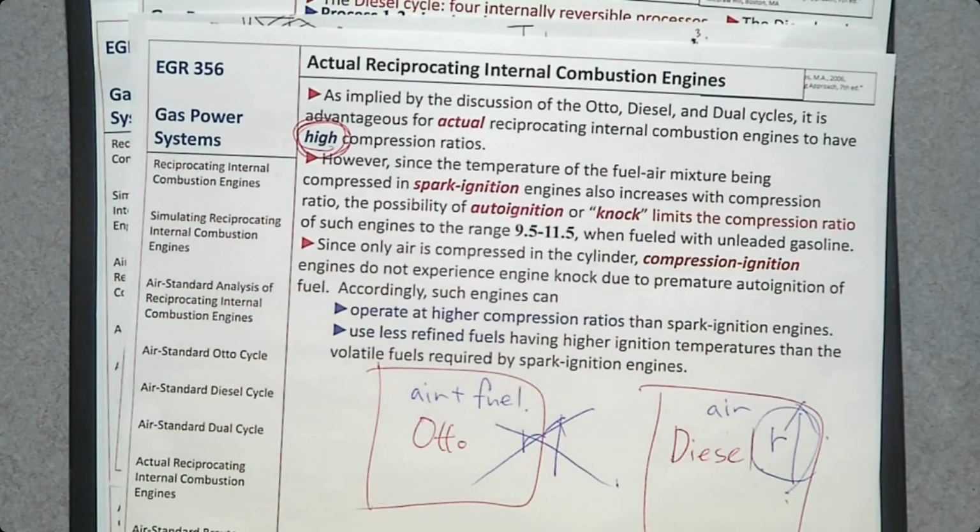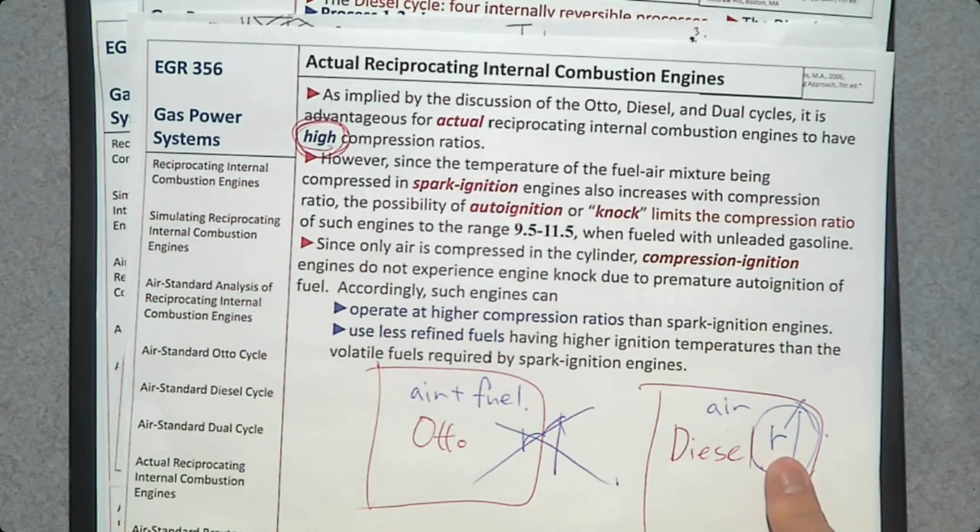Simply, you mix them, air and fuel, and inject into the engine, which is simple. However, to improve the compression ratio, you don't mix them, just inject air and then compress as much as you can. And when it is the right time to have an ignition, then you inject fuel in the system so that we can have a high compression ratio. Of course, this one is more complicated, more expensive, but has higher efficiency because of this r value. Okay,